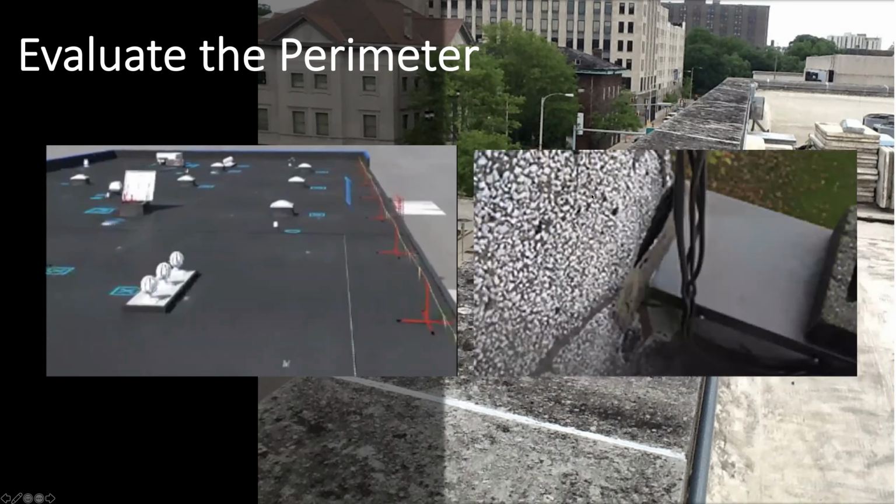Some compound type issues. We have aggregate wall panel here with, again, that metal coping. It was never flashed correctly, and regardless of the type of roof system, the roof's going to get blamed when the water comes down this wall and gets in. That's definitely an annual type of maintenance issue. And again, expansion, contraction with the different temperatures probably pops this open frequently.